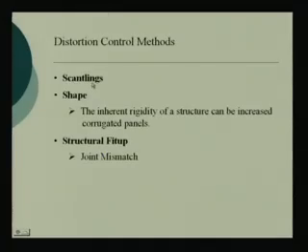That means, if I go for a little lesser strength to weight ratio, that means I increase the weight of the structure, I gain in terms of buckling strength, and because of that welding distortions will be less. That is an aspect on the production side one will have to see. So, while deciding on the scantlings, a higher scantling means always fewer chances of buckling.